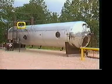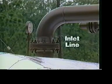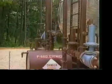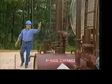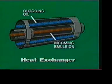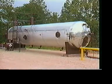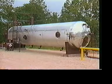Emulsions enter the heater treater through the inlet line, which may be located inside a heat exchanger on some units. Although this treater does not have a heat exchanger, some do. A heat exchanger is used to heat up the incoming emulsion and cool down the outgoing treated oil. This reduces the amount of heat necessary to treat the emulsion, and the cooler storage temperature minimizes vaporization and maintains a higher oil gravity.